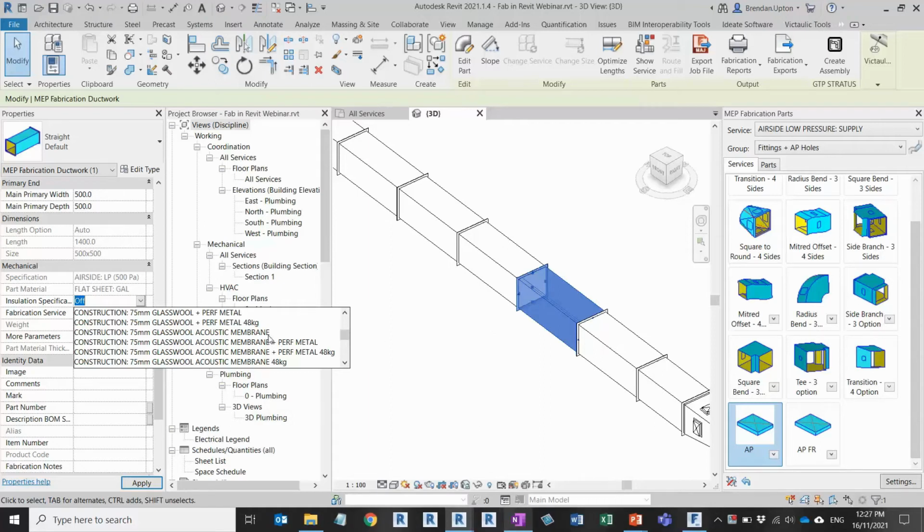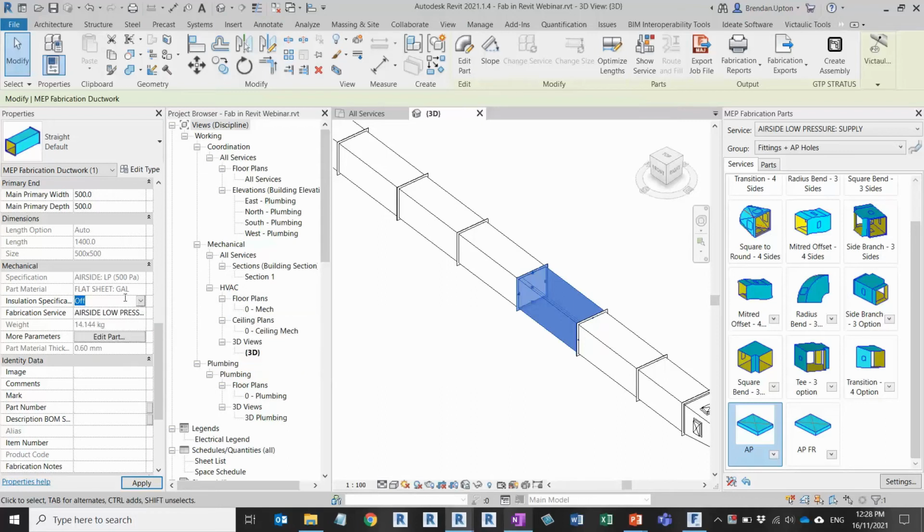So in terms of tagging, if you don't want to tag this whole long name, you do have the ability now in Revit to be able to tag those abbreviations, which we have added into these fabrication parts. Just as a heads up, you won't necessarily see the installation abbreviations within the properties here. It's not exposed within the properties as such, but when you're tagging, you will see an installation abbreviation field that you can use within tags. Just be aware of that.